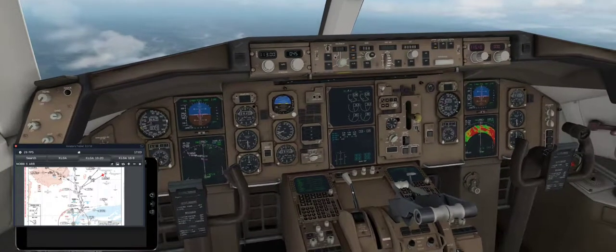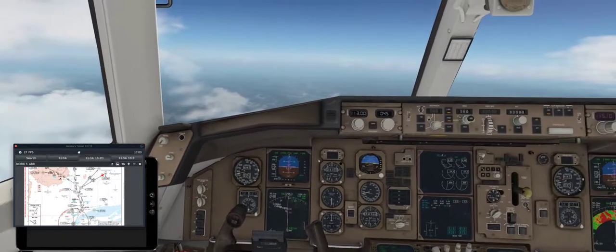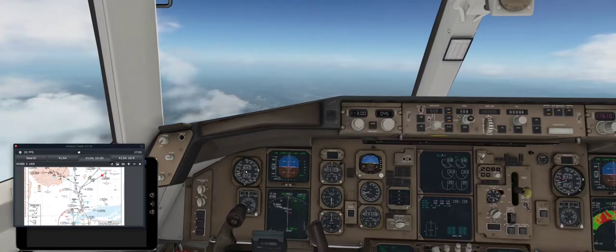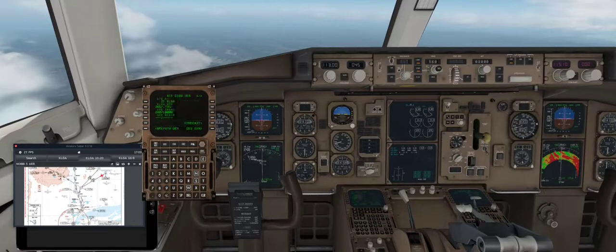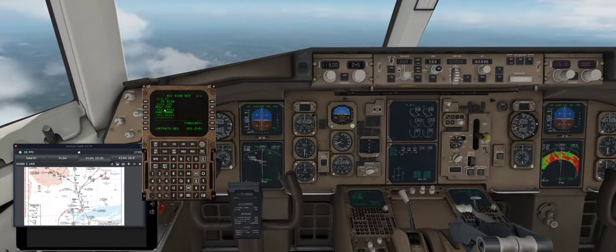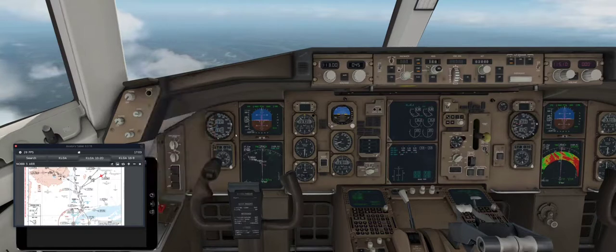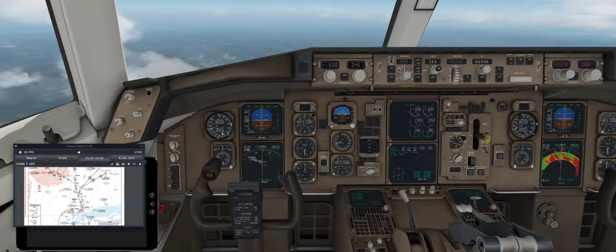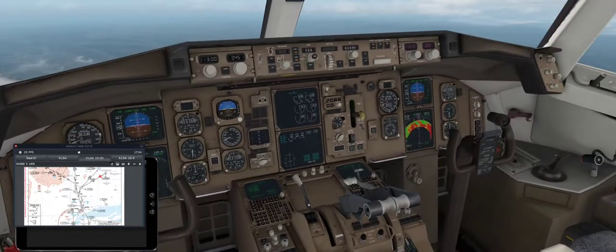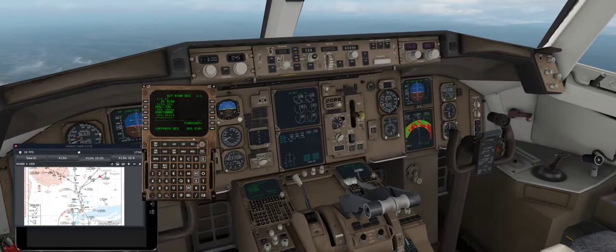Now we keep an eye out because we're probably going to have to apply the speed brakes in order to keep our airspeed where it needs to be. And where does it need to be? Well, that was this descent page over here. 0.73 Mach, or 265. Yep, that's where it's at, right here, 265. And it's coming down, so it's able to not overspeed the plan without using the speed brakes at this point. Here's the speed brakes. And we'll see if it becomes necessary. Our FMC will tell us.